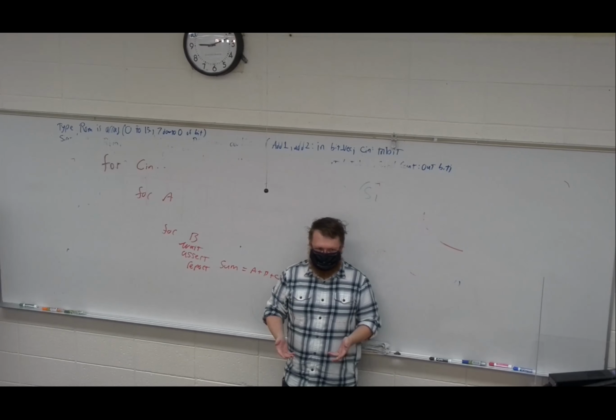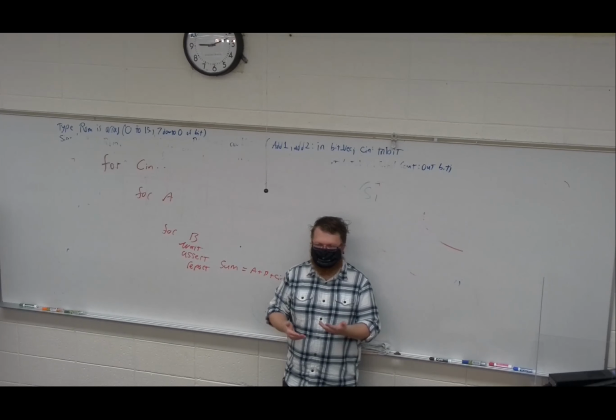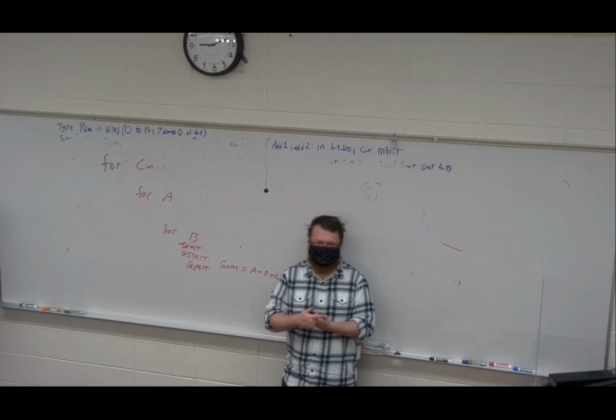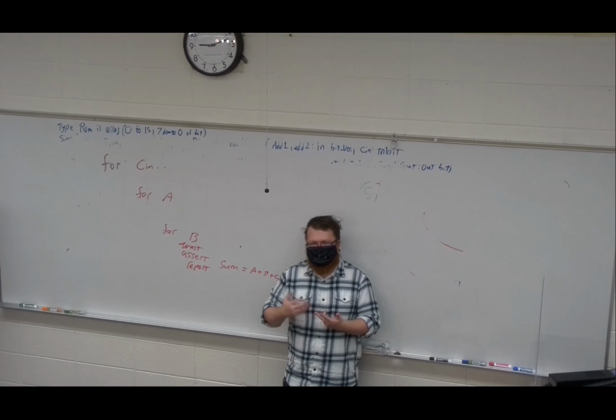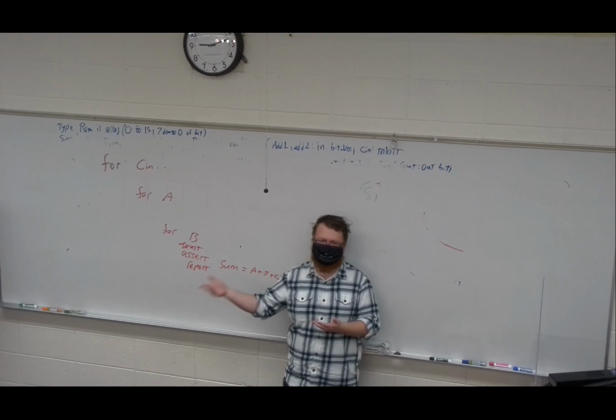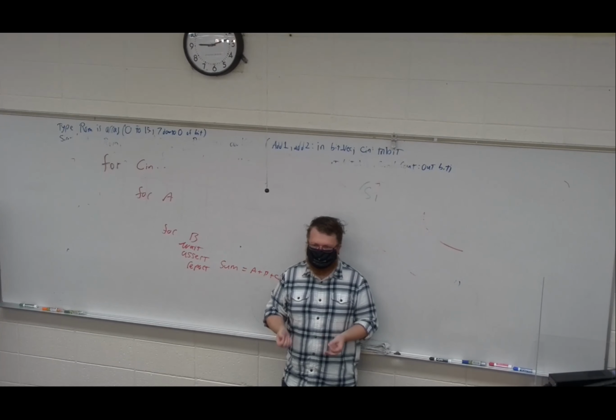If you're debugging, the first thing I always recommend dragging into that waveform is your state, because that's the most important thing. What state is having an issue? The second one is the counters, whatever it is that's keeping you in that state for a fixed amount of time. And then any signals that are pertinent to changing states. So if you're waiting for some condition to be true to leave a state, add that signal, because that's where most of your bugs are going to be, in state transitions.